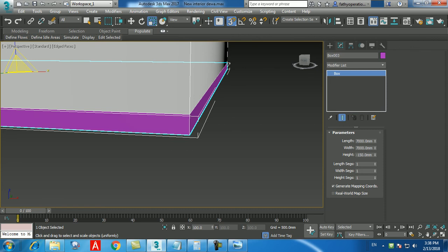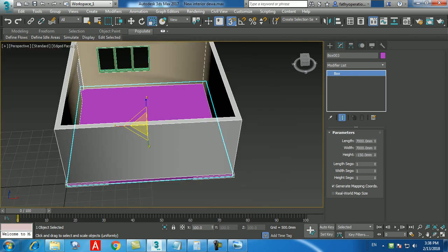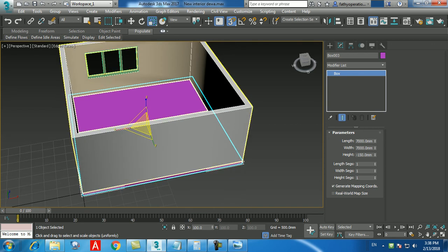Like a flooring area. You mean the material for the floor? Fill that inside. This is our concrete. That's the reason I put -150, pushing it down, as the structural floor. But here you don't have to focus on the inside tiles and stuff. We are not going to take quantity. We're just going to do presentation. Even if you want that, you can take the outer rectangle and inside rectangle and push down.